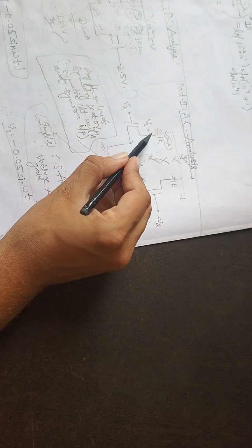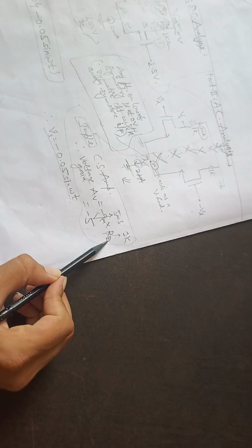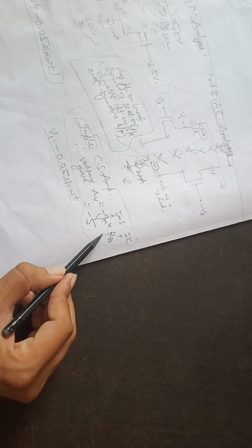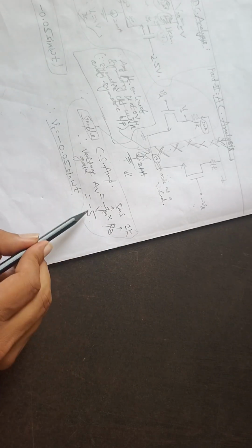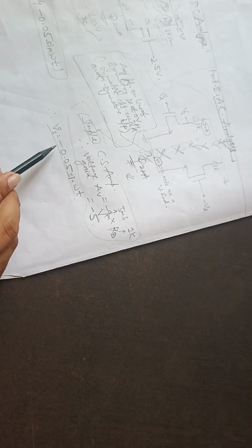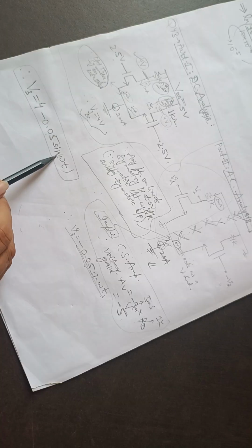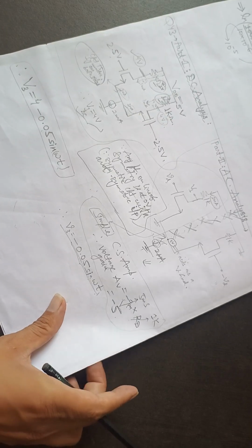this is basically a simple common source amplifier with voltage gain minus gm upon RD. So gm is 5 millisiemens and RD is 1 kilo, so the voltage gain will be minus 5 times the input, so the V3 AC output will be minus 0.05 sin omega t. So the overall output will be 4 minus 0.05 sin omega t. Okay.